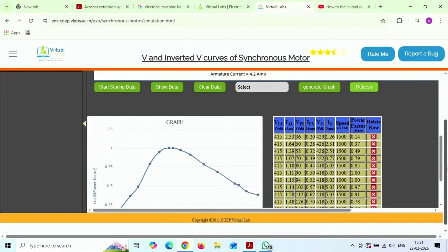We have subtransient reactance and transient reactance. Once the fault is cleared, what do we get? Synchronous reactance. We say impedance, but if the armature resistance is completely negligible, then we are finding reactances. Subtransient reactance does not last for a long time, usually 4 to 6 cycles. The balanced fault is sinusoidal only, right? Then the transient reactance varies from 6 cycles up to about 5 seconds.